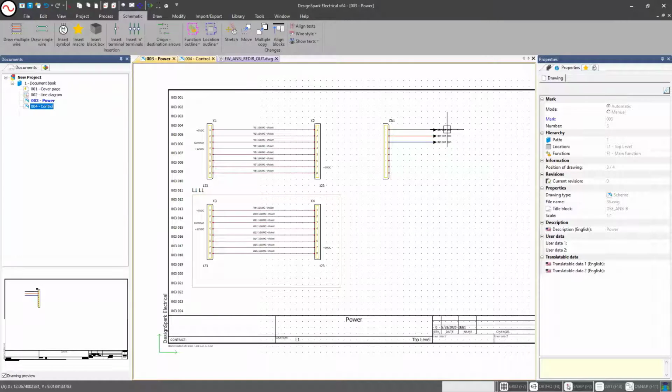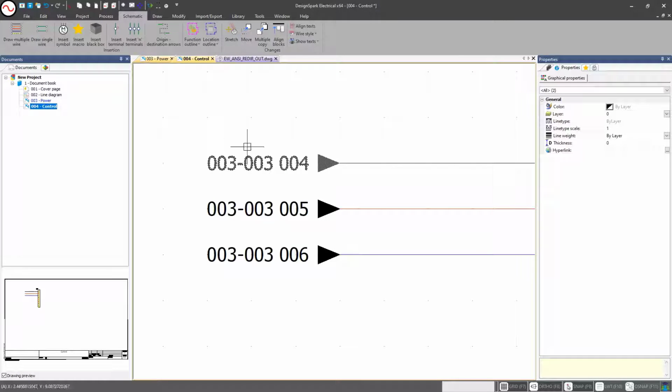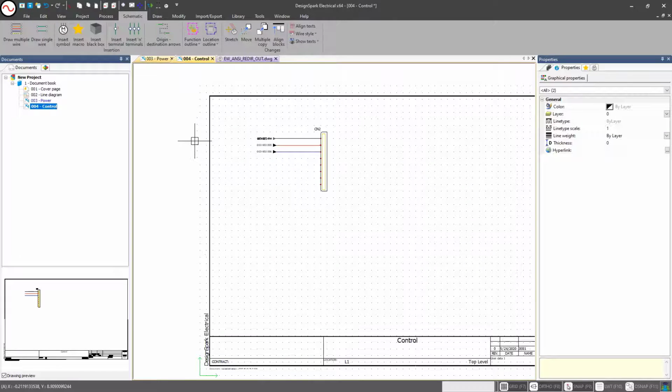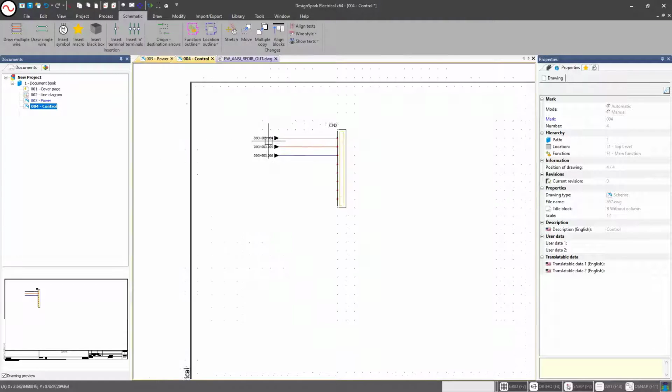The other nice thing with this is that if we double click them, they will take us to the opposing page of where these are connected. So if we are working on a very large schematic on one page, a very complex schematic, we can simply double click rather than having to try to zoom out and find the row and scan over if we need to. So inside of those symbols,